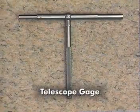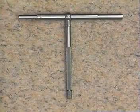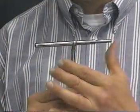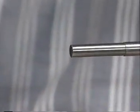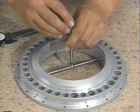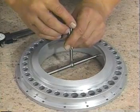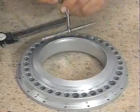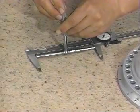The telescope gauge is a T-shaped tool in which the shaft of the T acts as a handle. The telescope gauge also incorporates telescoping plungers that have hardened radiused ends. Telescope gauges are used for measuring inside diameters. The compressed plungers are placed in a hole and then allowed to expand. The gauge is then locked, withdrawn, and the distance measured.